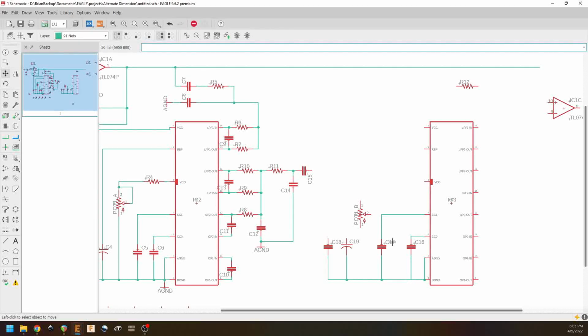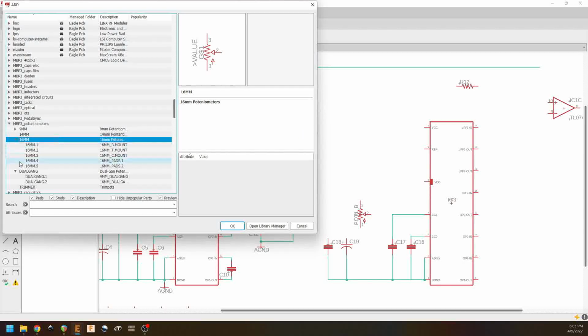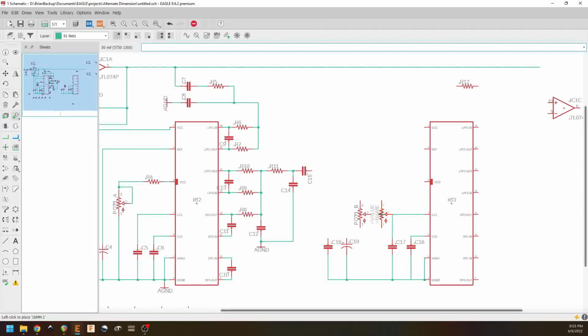on this second delay stage, we are going to need to put in basically two different time potentiometers, because we need to be able to take this guy on his own independent controls. So let's grab a 16 millimeter bottom mount potentiometer. We'll put him there.